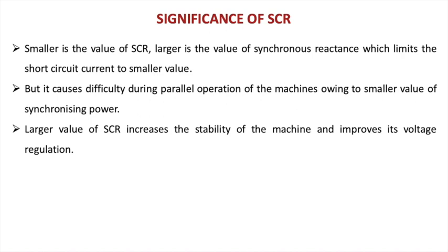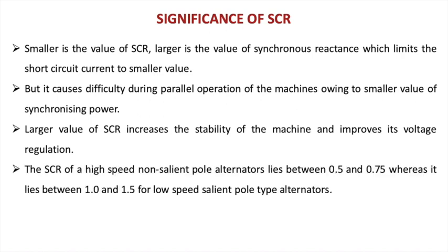If that delta increases above 90 degrees, the pole will slip to the other pole pair, which is known as out of step operation. So if the SCR is larger, the stability of the machine will be better and it improves the voltage regulation, that is, the drop under the loaded condition will be less.